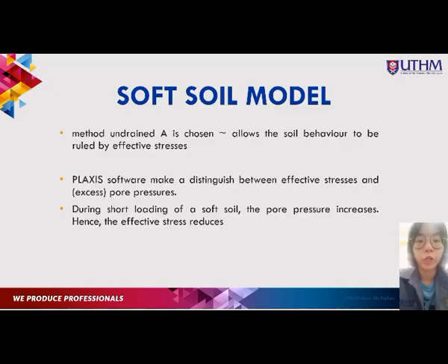For the soft soil model, we have chosen the method of undrained A, as there are 3 types of undrained method. However, method undrained A is chosen as it allows the soil behavior to be ruled by the effective stress instead of the pore pressure. By selecting this method, the software is able to distinguish between effective stress and excess pore pressure.